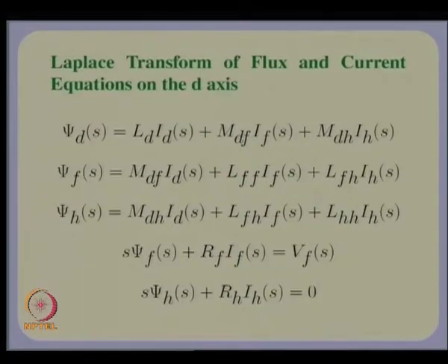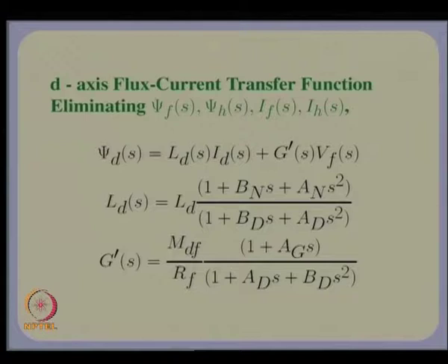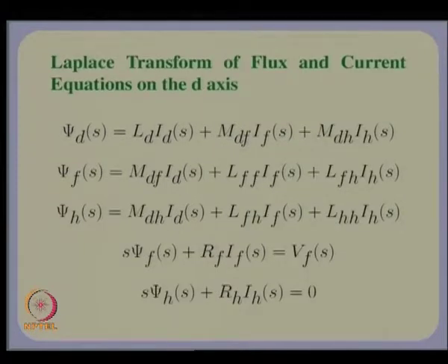But if I want a transfer function relationship between psi d and I d by eliminating psi f of s, psi h of s, I f of s and I h of s, I essentially use the first three equations, which are algebraic equations. The latter two equations are also algebraic, but they are obtained from differential equations on which we apply the Laplace transform. So, all of them are in fact algebraic equations.